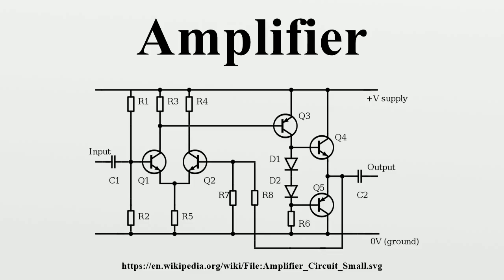Switched mode amplifiers. These nonlinear amplifiers have much higher efficiencies than linear amps, and are used where the power saving justifies the extra complexity. Negative resistance devices. Negative resistances can be used as amplifiers, such as the tunnel diode amplifier.